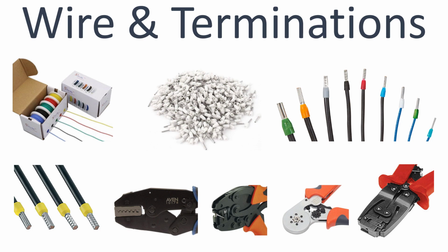I want to warn you, even though this crimps them flat, sometimes if you pull on the ferrule really hard, you can pull it off. Well, don't pull on it. Put it underneath the pressure pad for the screw and then run the screw down tight, and that will put an extra little crimp on it, and there's no way it's going to pull out of there if you've got the pressure pad down tight under the screw.